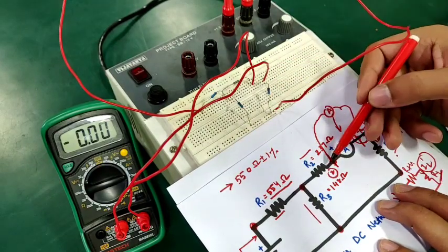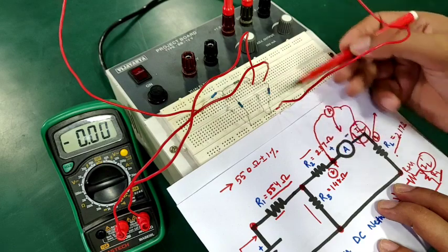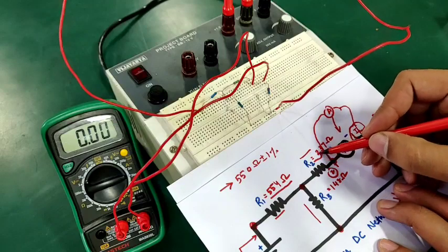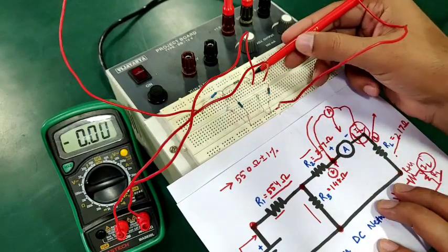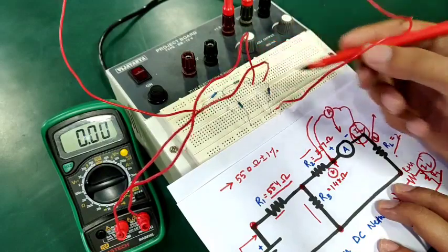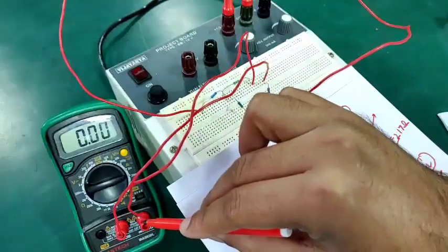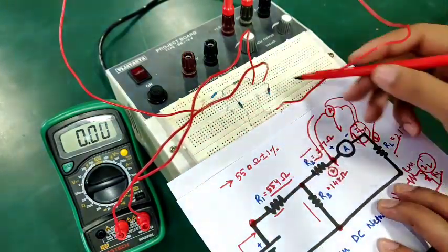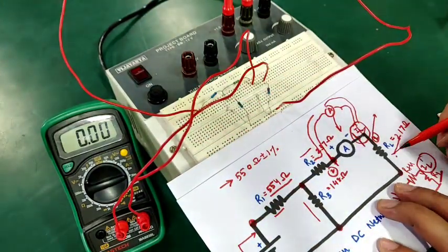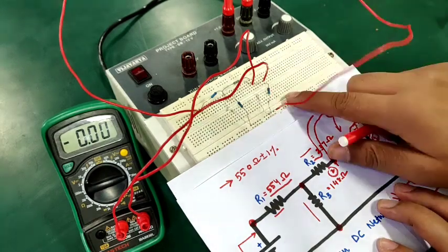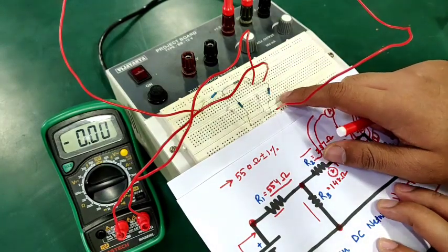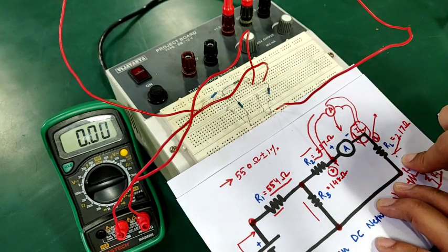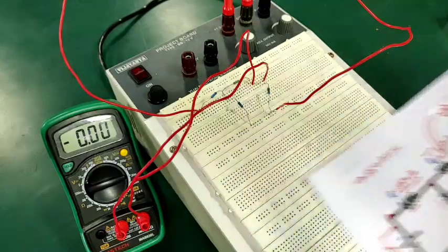Let us see where the second terminal of R2 is. This is the second terminal of R2, and after that current will flow like this through one terminal of the ammeter, which is here, and then back from the other terminal of the ammeter and onto RL. Alright. So this is how the connection of the ammeter looks if we want to calculate current through resistance RL. So I have connected the ammeter here.